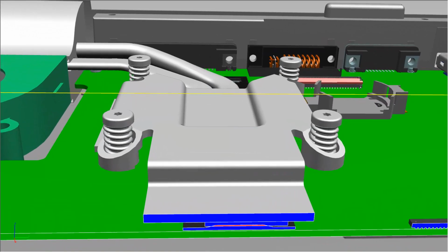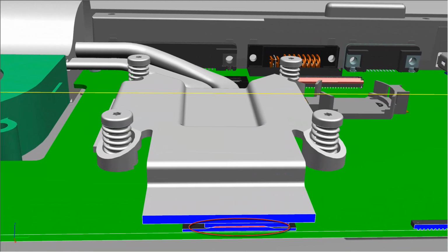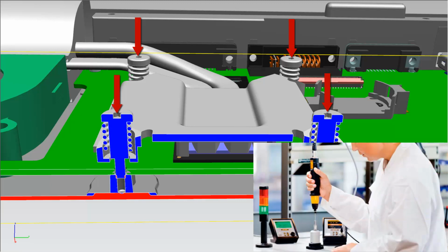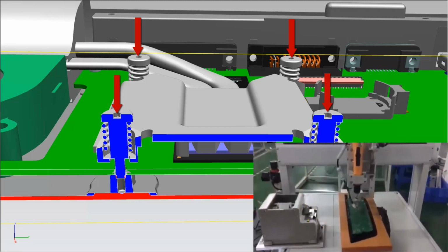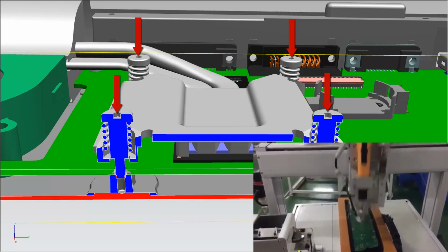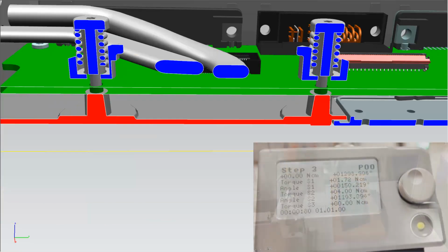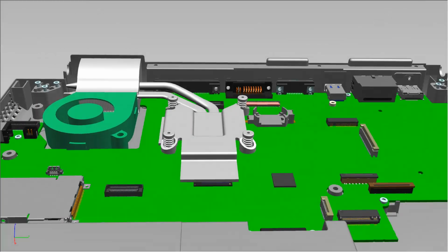The gap between the cooling plate and GPU has a similar clearance requirement. All these gaps are controlled by the 4 spring-loaded screws that secure the cooling plate to the standoffs on the base housing. All 4 spring-loaded screws are tightened down manually or automatically with a digital micro-torque screwdriver at preset torques that usually vary in a ±6% range. Therefore, setting the torque at the proper value is the key to achieving desired gaps, hence delivering optimal processor performance, minimum fan noise, and Six Sigma quality.